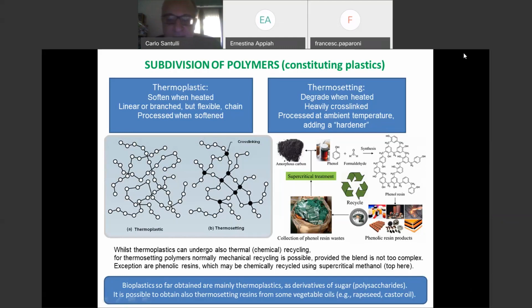There are a number of questions. So thermosetting plastics, of course, don't soften because they have a reticular structure, basically a cross-linked structure, which tends not to deform with temperature, and therefore it doesn't break the linkage and it doesn't soften in the usual interval.